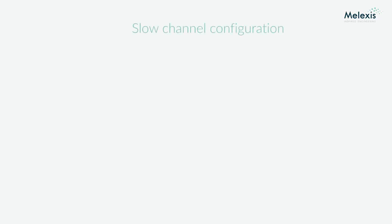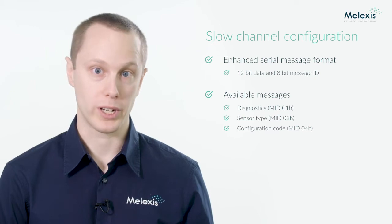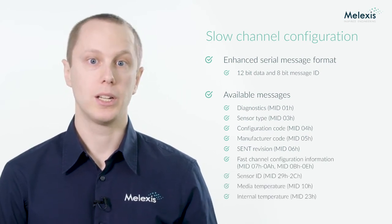The product's slow channel messages support the enhanced serial message format, using 12-bit data content and an 8-bit message ID. There are a large number of messages available that already have a fixed message ID, as they are clearly defined in the SENT standard and most often used in current applications. These messages contain information like diagnostics, sensor type, product configuration code, manufacturer code, SENT revision, fast channel configuration information, sensor ID, media temperature, and internal temperature.